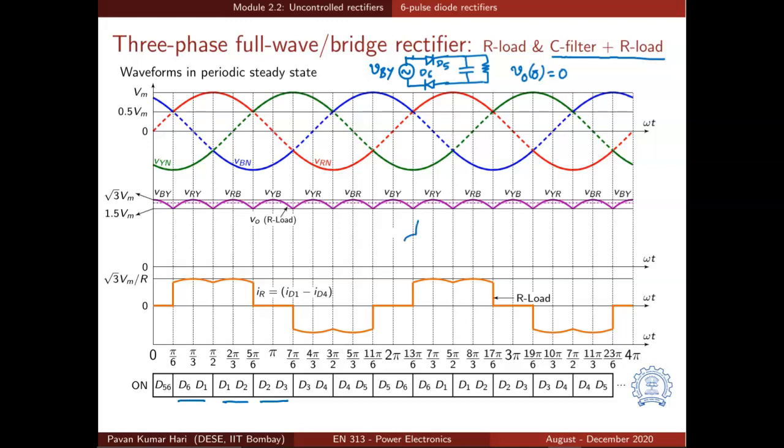Now what is the circuit that we are looking at? We have a circuit like this. We have this voltage source, then you have these diodes which can be represented by short circuit. You have a capacitor and you have another diode to close the current path, and of course you have a resistor. There is nothing to limit the flow of current in this loop. So what happens? Huge amount of current is drawn, and the capacitor charges to certain voltage.